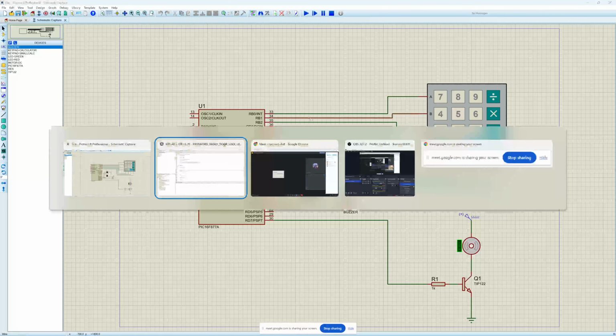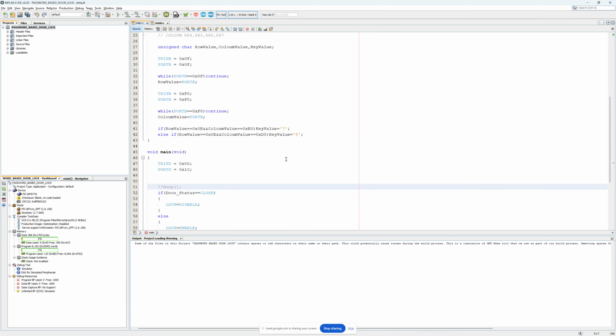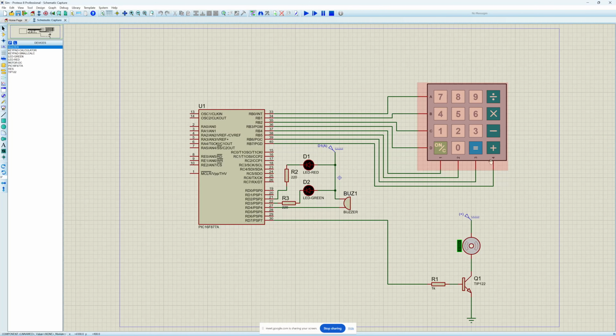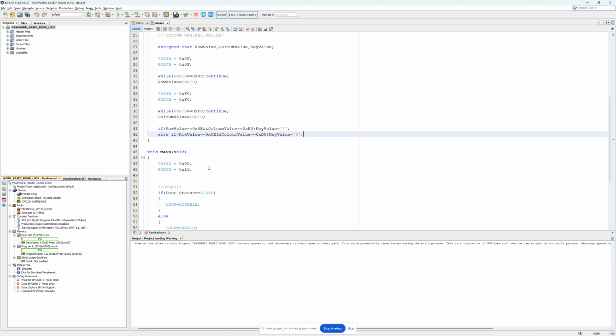It is almost finished. We wrote the code for how we can retrieve a particular key from the keyboard. We wrote till this line, I mean 7 and 8. We have a few keys remaining to add. Before that we will test our code to see whether the keys are working properly. For that we need the support of our UART to see whether the values are coming exactly as we needed.